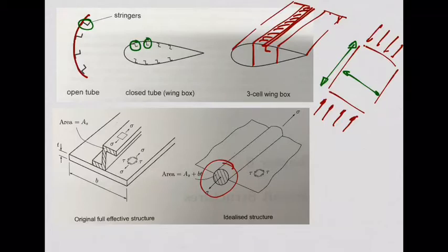So we have a lot of these components inside the wing that we call the wing box. They are spars. Imagine, for example, I have an I-shaped spar, Z stringers. I can have another Z stringer here, another Z stringer here at the bottom skin, more Z stringers, and so on.